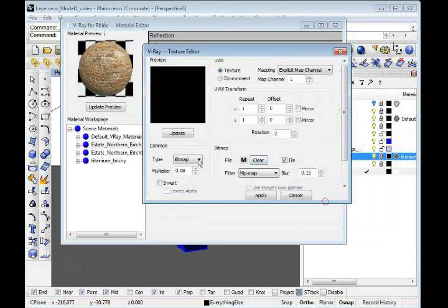Okay, so click that. Here you'll notice the multiplier. The multiplier tells you how intense you want that material to be. It should be set to probably 1.13 or 0.13. I've reduced mine to 0.05 to reduce the amount of bump effect that it has on the material.